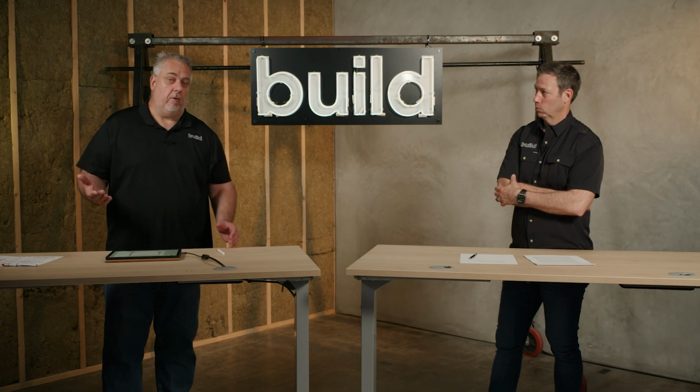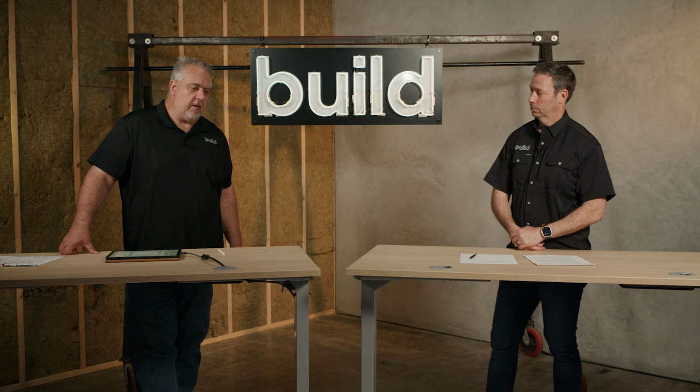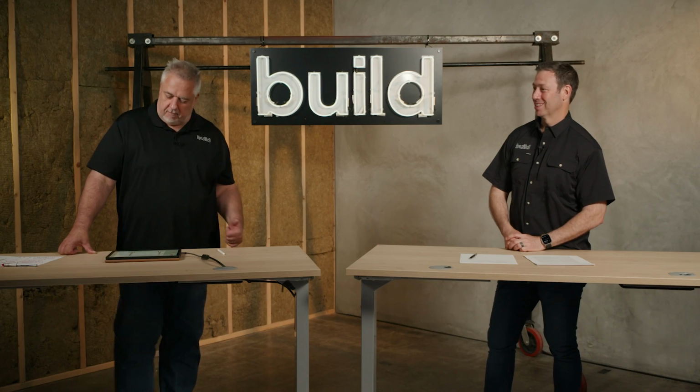Continuity is the key. It is the number 1 concept of airtightness. The way I was taught airtightness is to think of it as a leak in a boat. You don't want 1,000 little ones. You don't want 100 medium-sized ones, and you sure as hell don't want one big one. That's for sure. You don't want any leaks. Your bilge pump's not going to keep up with a real big one, is it?